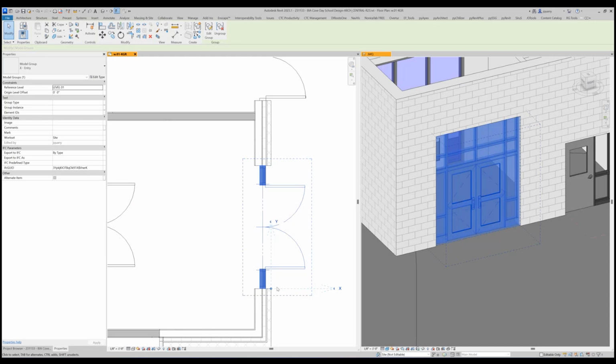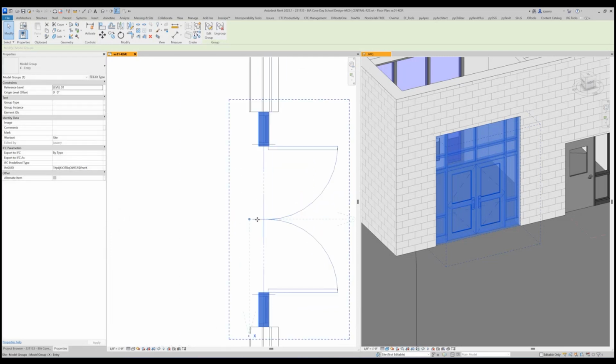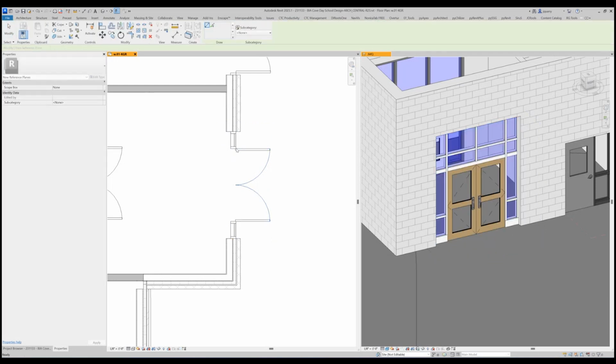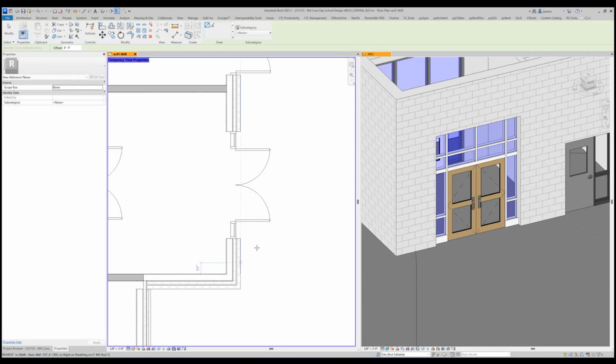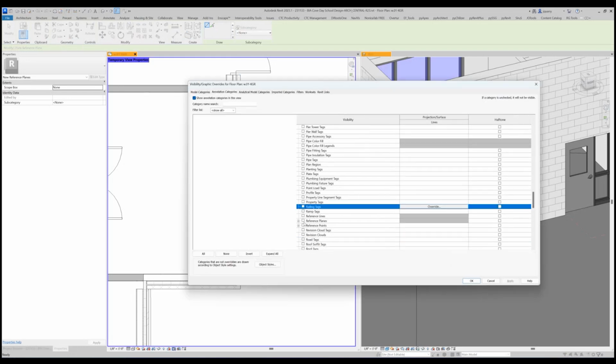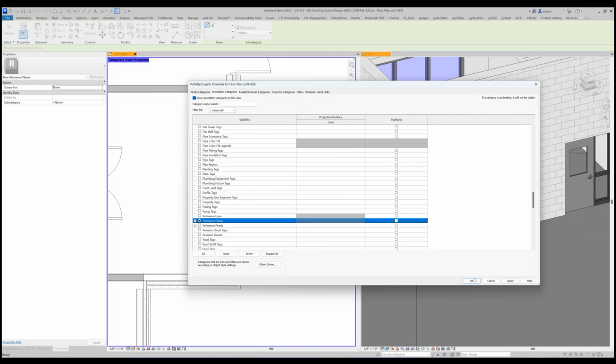Okay. So this could be in the middle, could be right there, and then you can move it to the center of the door if you can find it, which you might have to do some additional work to find the exact center. Then you can rotate this so it's X and Y. To find the true center, I would do this reference plane here, and let's use the temporary one, because reference planes are something that sometimes you want on, and then most of the time you want off.